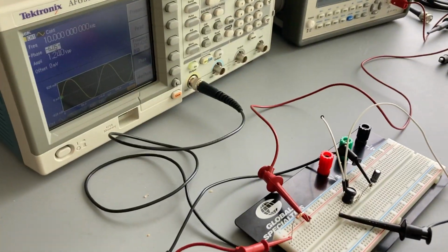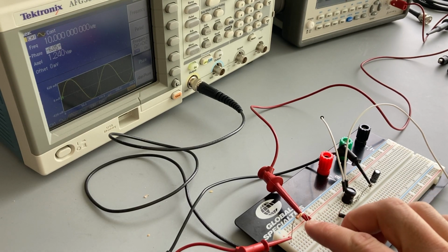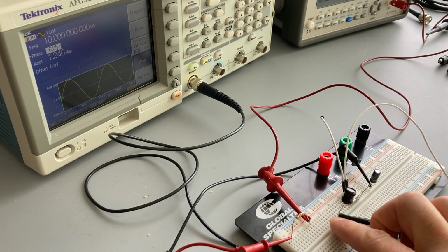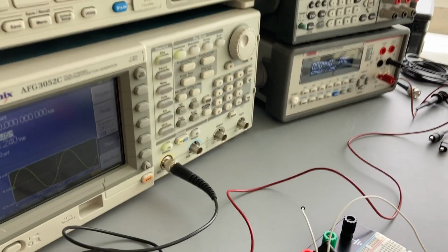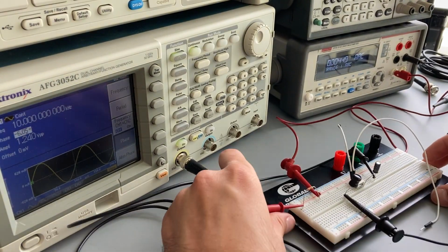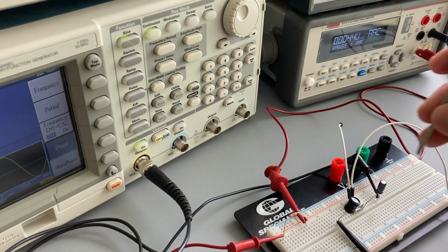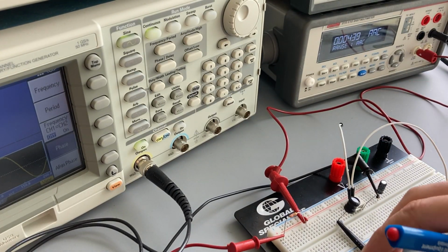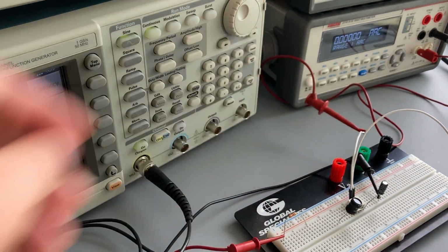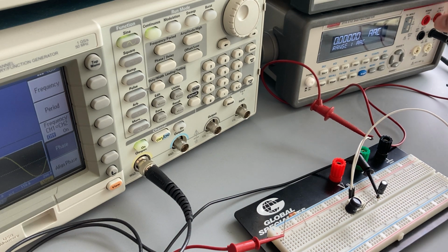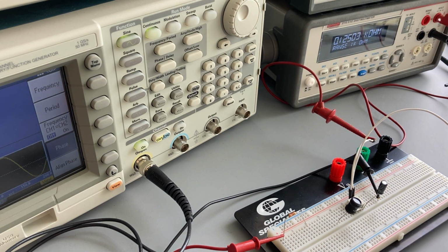So turning to the physical circuit, here I have my resistor. I have a separation between my resistor and my inductor, so I can quickly switch between doing current measurements and resistance measurements. So let me move this in the way here so we can actually see. So I take a small screwdriver, and what I'll do, I'll switch to a current or a resistance measurement. I make a resistance measurement here.